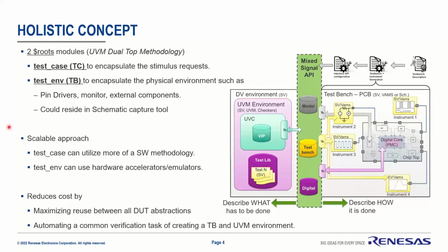So the concept we have is using the UVM dual top methodology. We have two $root modules: a TestCase, a module that just encapsulates all the stimulus, all the class-based software layer, and the TestEnv, which encapsulates all your physical stuff: your pin drivers, monitors, external components. It's basically what your PCB would look like. And ideally, as we'll see later, having that TestEnv reside in a schematic capture tool has benefits.